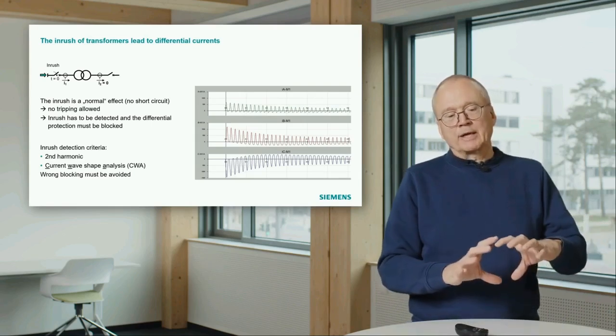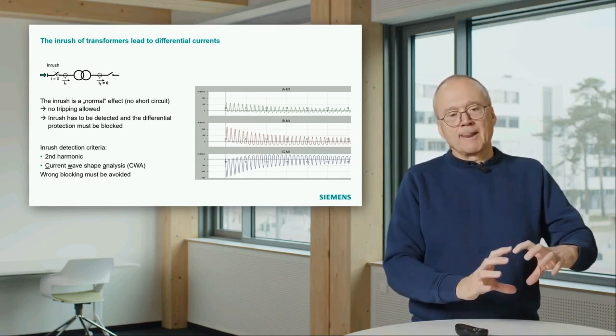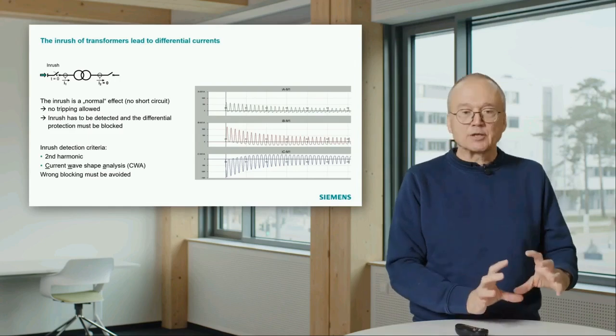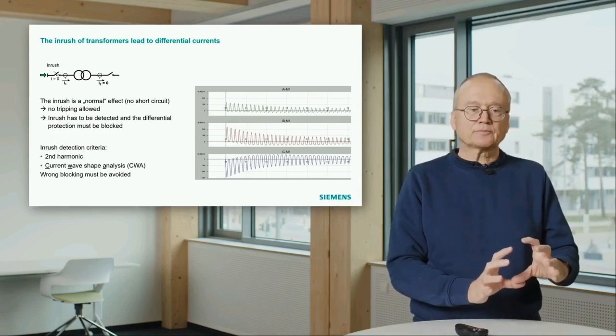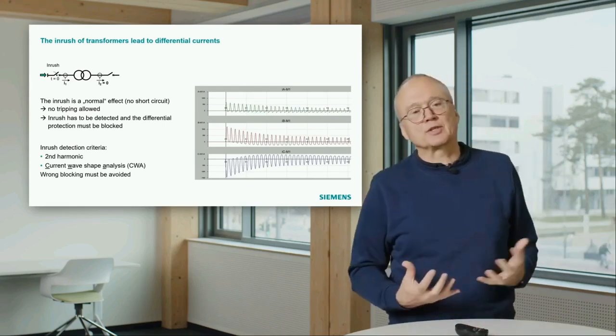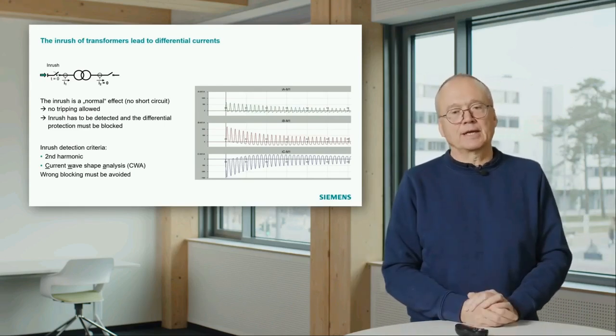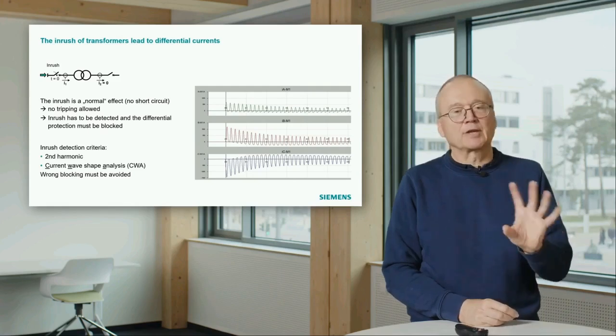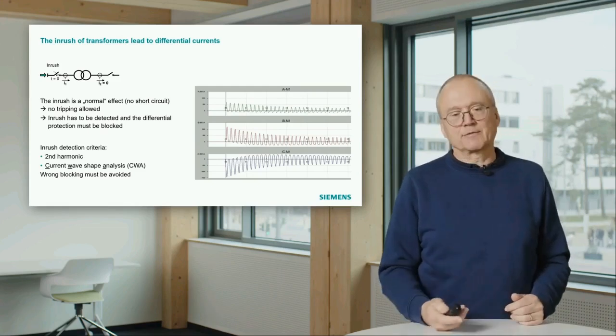Normally the blocking affects only the sensitive part of the algorithms. That means there is no risk that high current faults are also blocked, but nevertheless that is a sensitive thing.